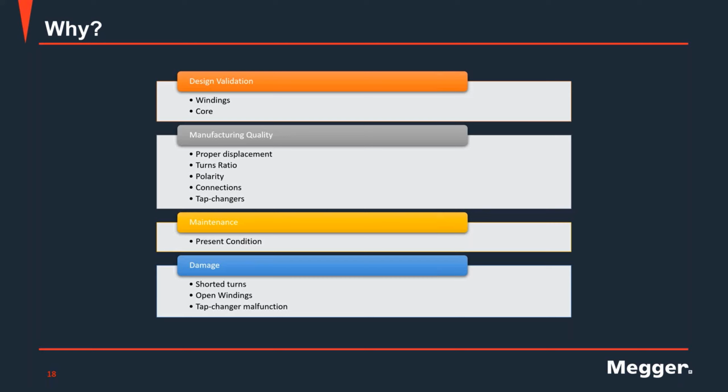We can assemble the windings or connect them in an incorrect way, and also, when constructing the necessary vector configuration of a Y or a delta, mistakes can be made during manufacturing. Insulation failure, right? When we have damage in the turn-to-turn insulation that will result in shorted windings, it's something that will be reflected in the TTR results.